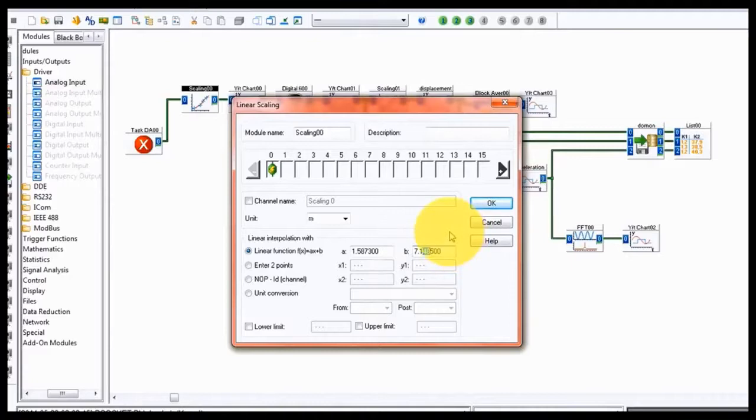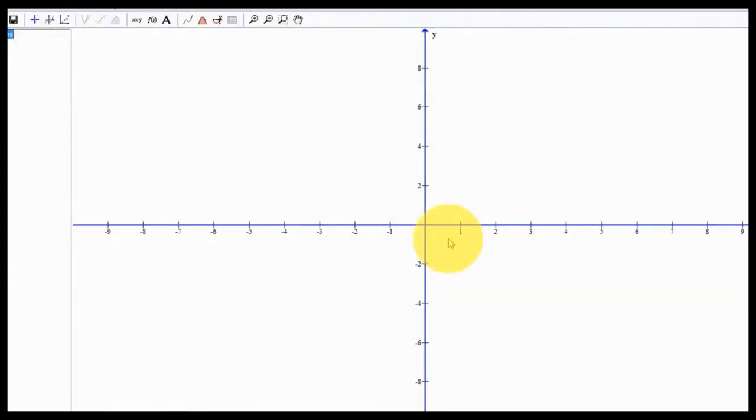between displacement and voltage. First we need to draw the graph between displacement and voltage by using data we calculated manually. Now that we are going to plot the graph between displacement and voltage, we need the voltage value from DASYLab and the displacement from manual measurement when a certain load is applied to the spring system.